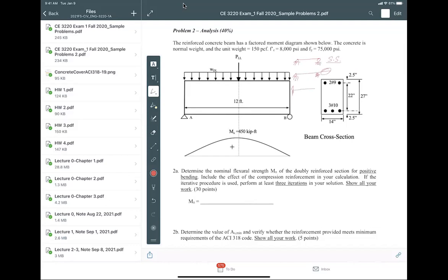Why I love cantilever so much is because if I do a cross-section cut here, you know that the reinforcement in tension is going to be on top. Is that right? Now, fortunately for this practice set, it is simply supported, meaning the tensile reinforcement is here, the 3 number 10 bars. But be careful in the exam. If you see a cantilever and I'm showing this, then the real tension bars will be 2 number 9. You got to flip the section. Tricky. So be careful about it.